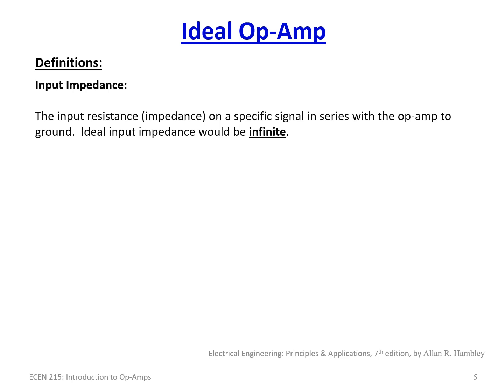Input impedance, as you've seen before when we've talked about resistance or impedance, refers to the load on V1 and/or V2. Ideally, it would be infinite. There would be no load on the input value. You read that voltage, but you would not apply a load on it. So ideally, the input impedance of an ideal op amp would be infinite ohms, so it does not cause a load on the input signal.